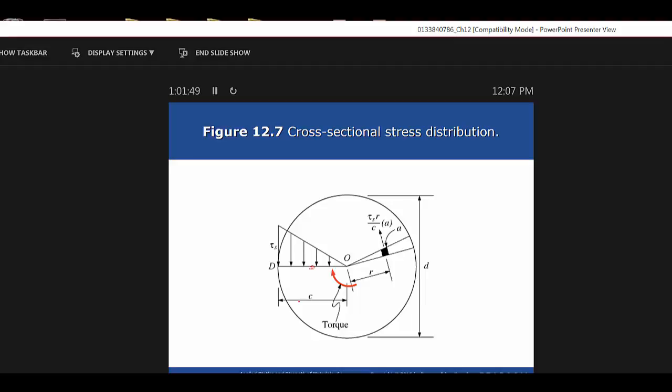And then the C value. It was 75 millimeters, actually that's the radius, isn't it? The diameter is 150 millimeters, so C is a radial value. You just take the diameter divided by 2. Your answer is 55 times 10 to the 6 Newton millimeters, and then they just changed it to kilonewton meters.